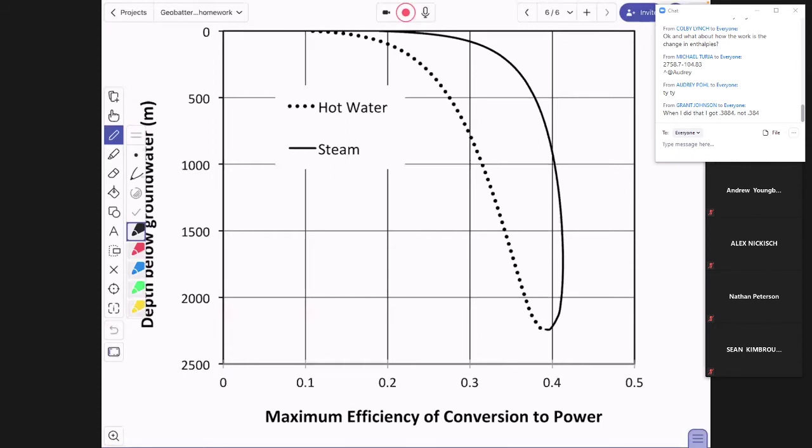There's a different curve, and we'll be talking about this a little bit later in the semester. There's another property that we haven't talked about that is called exergy. Some people call it availability. Some people call it Gibbs free energy. We'll be learning about that after we learn a little bit about entropy. What Gibbs free energy gives us is information on the capacity of that fluid to be converted into work. If I put work in without any losses, all I'm doing is increasing the exergy. So exergy is the potential to do work.